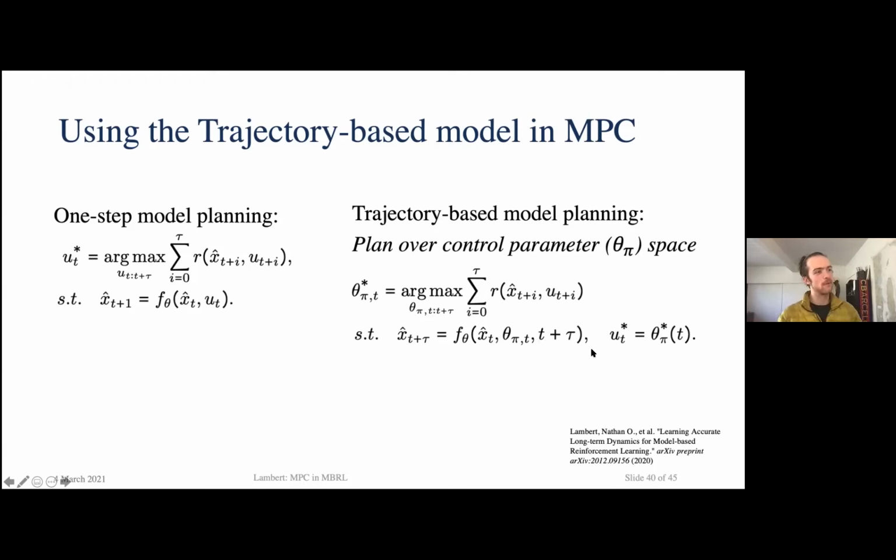So when implementing this with something like PID, it's somewhat tricky because you have to run your planning as if you are changing the PID parameter at each step as you plan into the future. You can't just create a new controller easily, which is something that actions have that is nice. It's a little bit easier in an MDP to just throw a new action at it and see what happens. Planning over the control sequence takes a bit more of a nuanced actual implementation